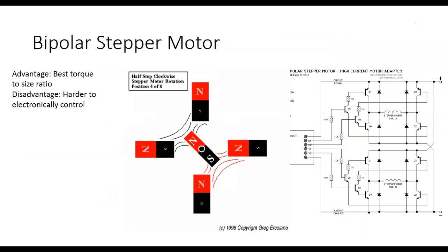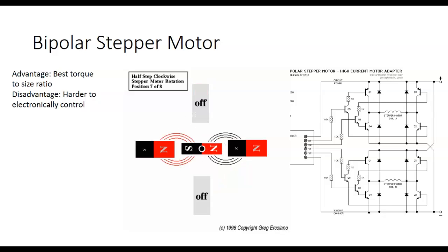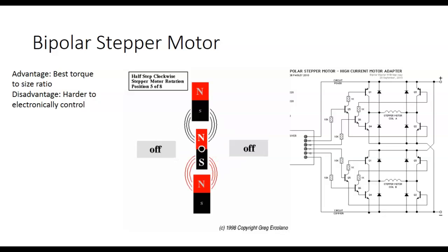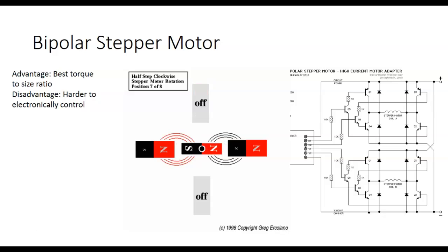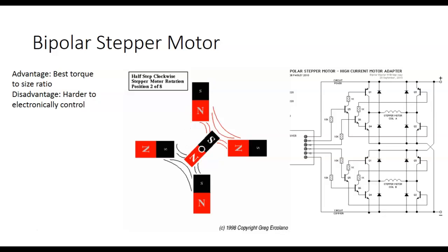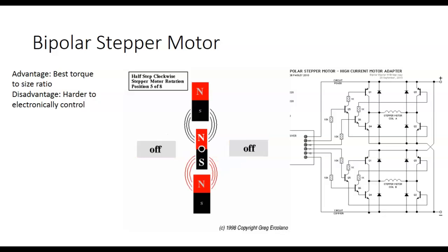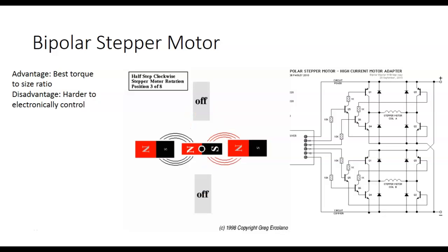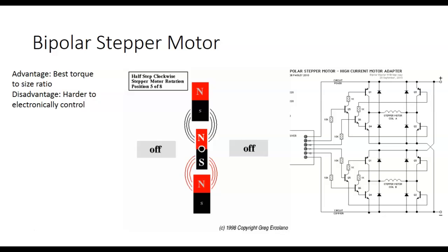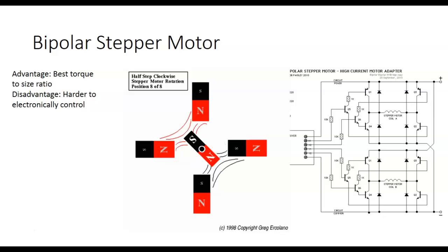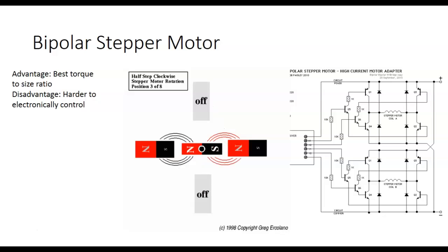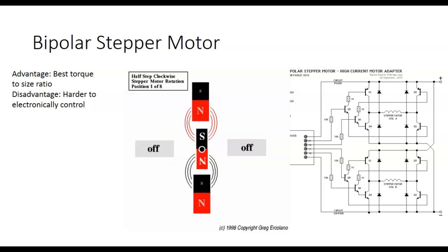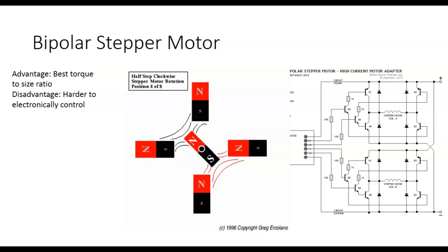Bipolar stepping motors: basically, stepping motors have a permanent magnet rotor, and then what we do is we electronically move the field. Oh, by the way, this is called half stepping. If you have the electronics and know-how, notice it's actually energizing two fields at the same time. So this has 8 steps instead of 4 steps. You can buy these double step controllers. We don't have any around here, so my program just single steps.